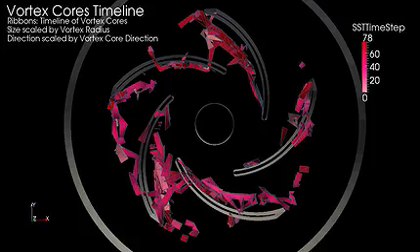To provide the ability to compare vortex locations from two or more simulations over time, we developed a ribbon summarization technique that displays the entire time series in one image with minimal geometry. The timeline path of the vortex course produced by the SST simulation is visualized using ribbons. Each ribbon's center moves from the initial time step through the final time step, tracking a single vortex.